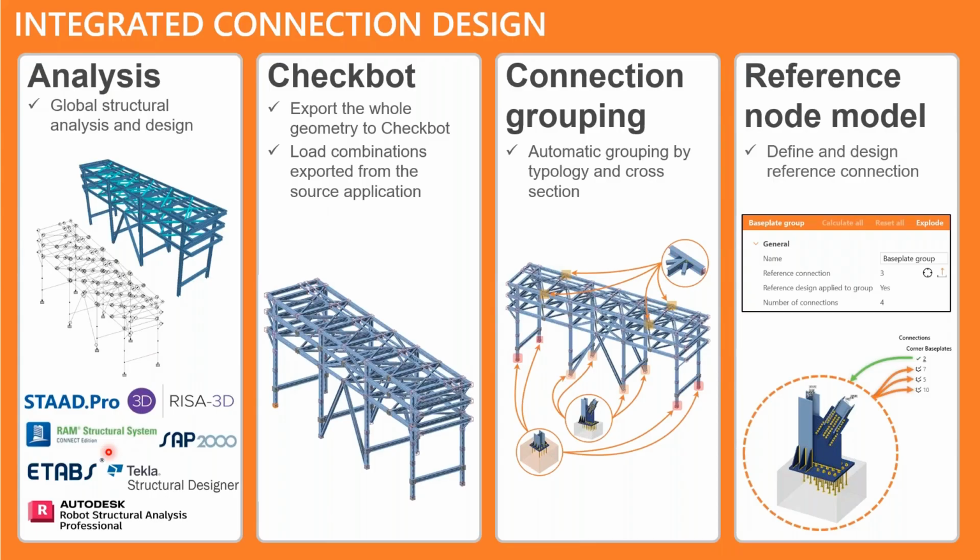The geometry and loads will be imported into Checkbot, and then later Checkbot will group the connections by typology and cross sections. Within these groups, a reference connection is defined, which will be the parent connection. This is the only connection that you will design for the group, and later the application will apply it to all the joints in that group.